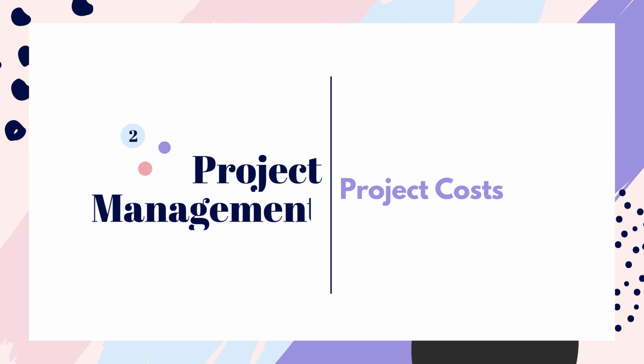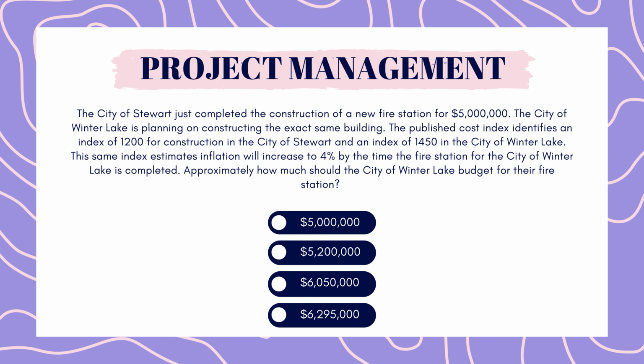Now on to project management. The City of Stuart just completed the construction of a new fire station for $5 million. The City of Winter Lake is planning on constructing the exact same building. The published cost index identifies the index of 1200 for the construction in the City of Stuart and an index of 1450 in the City of Winter Lake. This same index estimates inflation will increase to 4% by the time the fire station for the City of Winter Lake is completed. Approximately how much does the City of Winter Lake budget for their fire station?